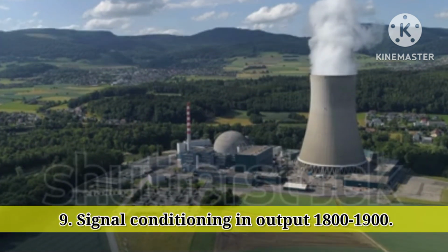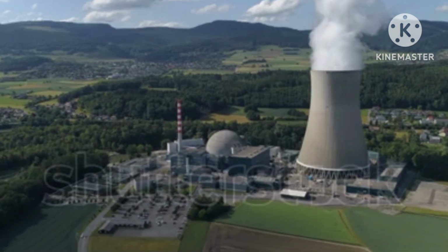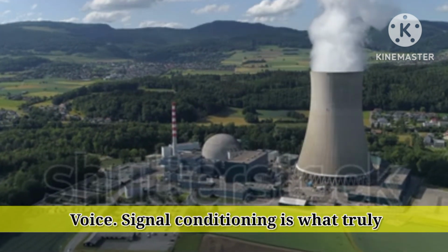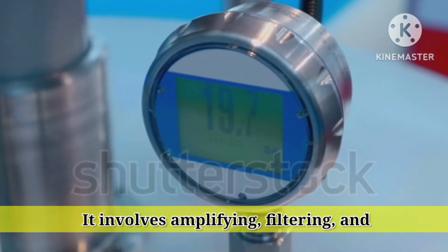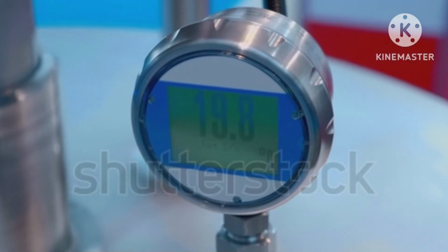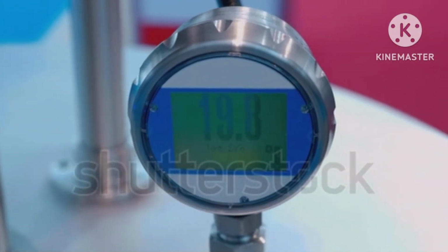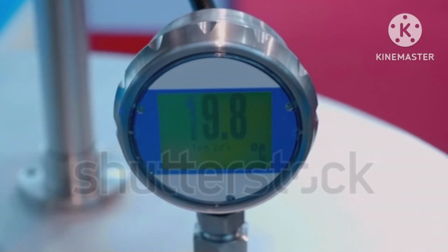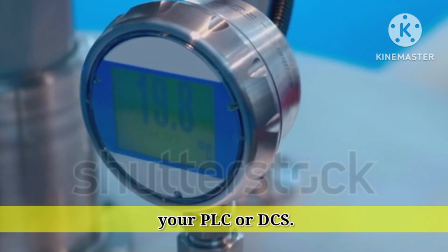9. Signal conditioning and output. Signal conditioning is what truly separates a transducer from a basic sensor. It involves amplifying, filtering, and converting the signal into a form suitable for controllers or recorders. That's why a transducer is a complete measurement package, ready to communicate with your PLC or DCS.